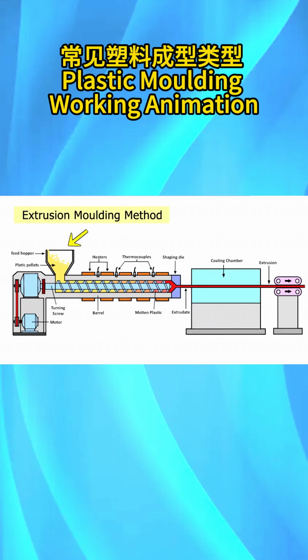In extrusion process, the dry plastic material is placed into hopper and fed into long heating chamber. Here turning screw pushes the plastic into barrel where heater increases temperature and melted polymer is obtained. At the end of chamber, the material is forced out of a small opening or a die in the shape of desired finished product. As the plastic exits the die, it is placed on conveyor belt where it is allowed to cool. This process of extrusion is usually used to make products such as film, continuous sheeting, tubes, profile shapes, rods, filaments, cords and cables.